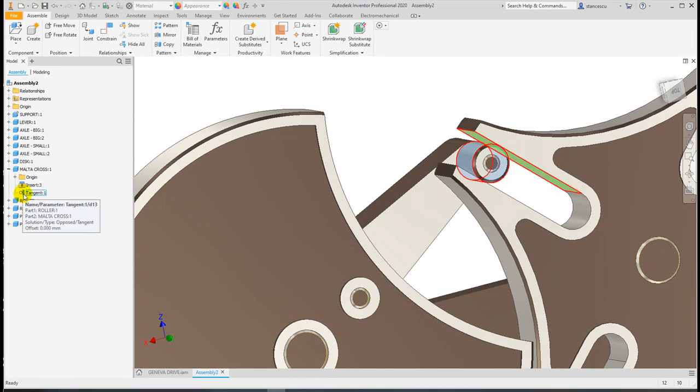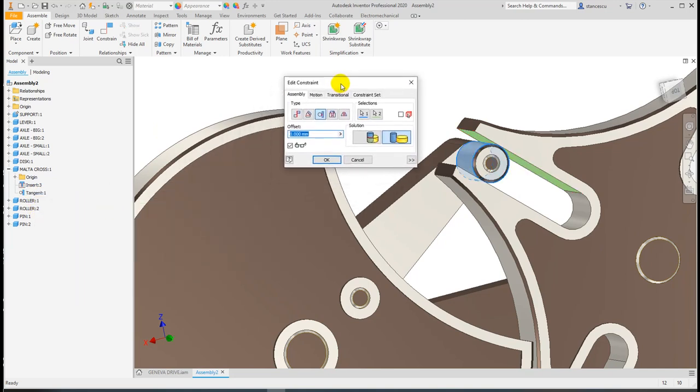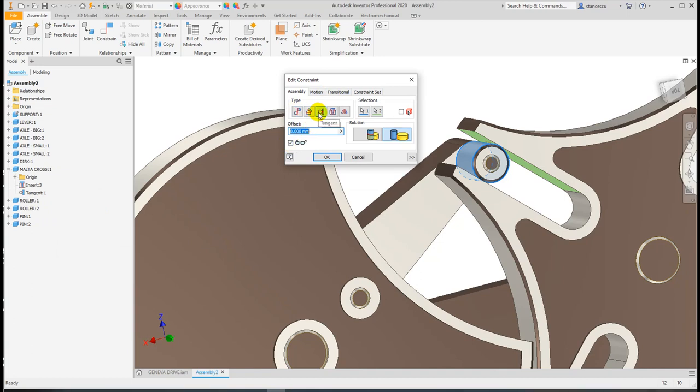If I move the cursor here, I see how is presented that tangency. I click here, I leave it alone, and I see this. Oh, I know what is, and what can I do? I can right click here and I choose edit, and instead of applying a simple tangency, exterior with interior, this tangent is on exterior and this tangent is on interior of the part. I can choose